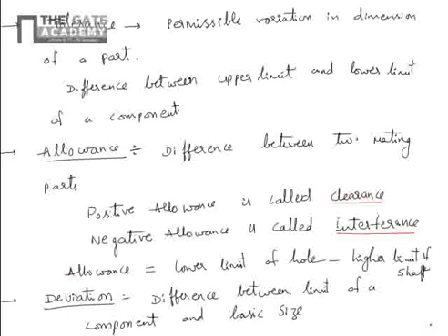It is the standard size with reference to which the limits of variation of a component are measured. If you calculate the diameter of a shaft to withstand a certain speed, you may get 44.95 mm diameter, but that is the actual size, based on the design value.